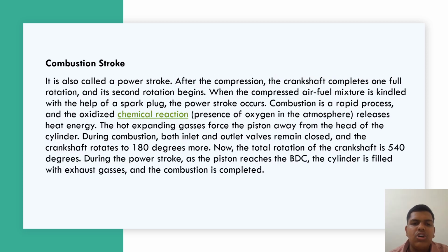Combustion stroke, also called the power stroke. After the compression, the crankshaft completes one full rotation and its second rotation begins. When the compressed air-fuel mixture is ignited with the help of a spark plug, the power stroke occurs. Combustion is a rapid process of oxidizing chemical reactions that releases heat energy.